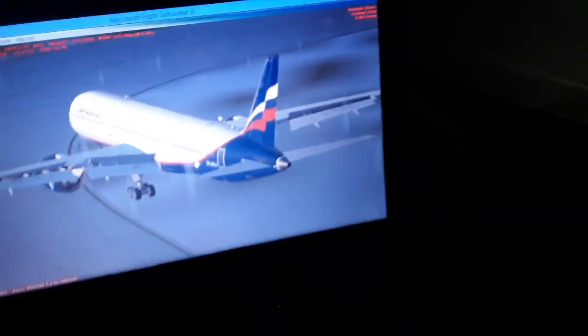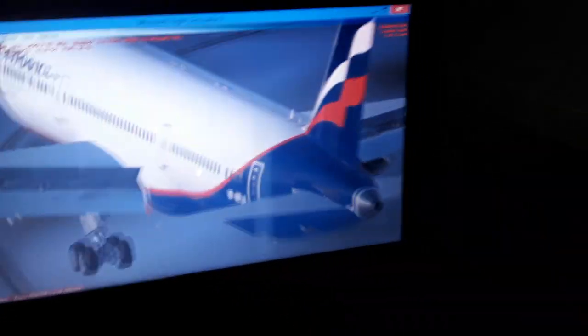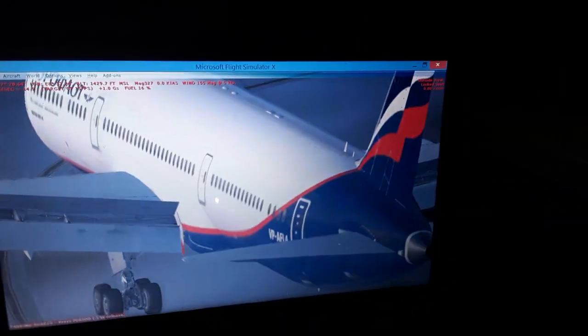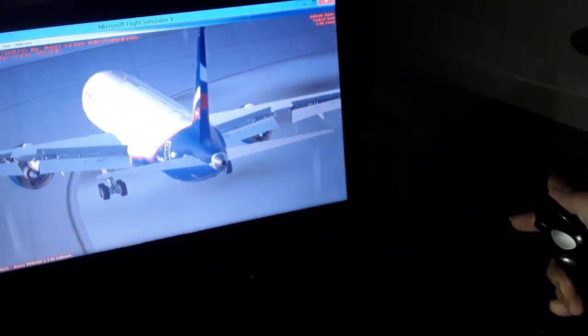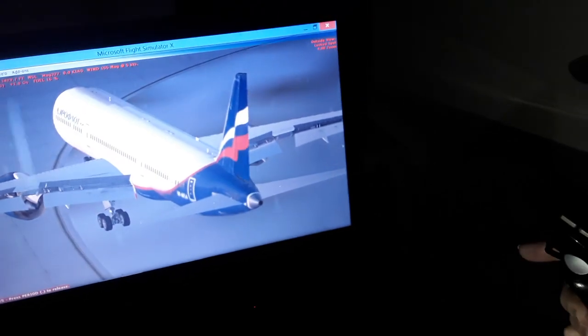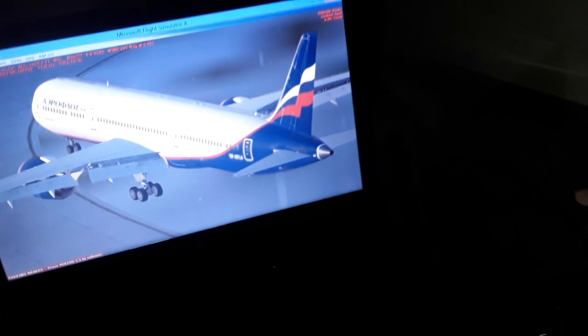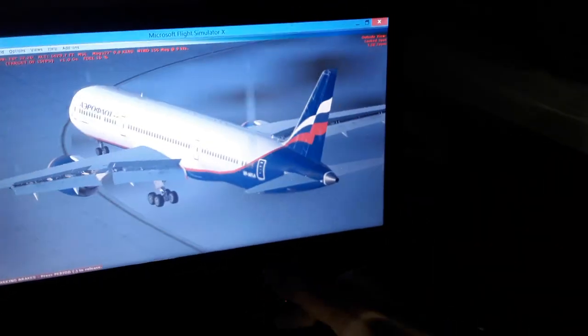Climb, descend, use the horizontal trim stabilizer, which we also have for the horizontal stabilizer here in the elevator. As we climb and descend, we can use the horizontal trim of the aircraft, for the Boeing or the Airbus aircraft. We can trim the aircraft stabilizer in the air so we can balance the aircraft. We can use the rudder pedals, left and right, for directional control, yaw turns in the air and on the ground. Also ailerons and spoilers make left and right bank roll turns as you can see.